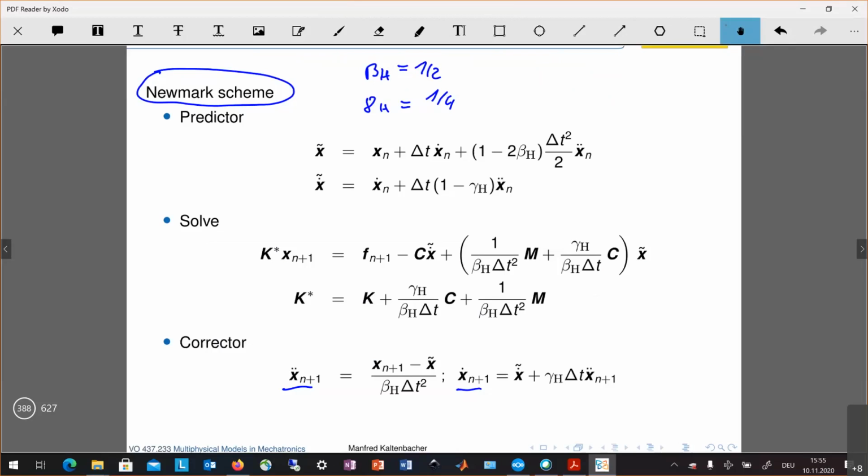We just have to approximate each component of the unknown displacement vector, the x, y, and z component, and in the standard approach you use there also the same basis function for the three different components ux, uy, and uz. Time discretization is similar as we have discussed for the heat equation.